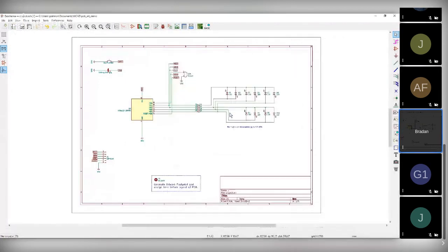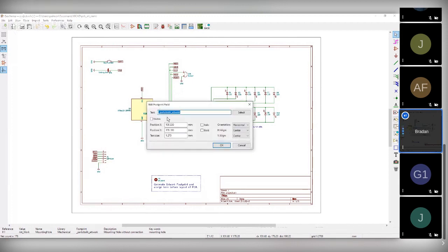How did you prevent that artwork attachment hole from being a hole? So the way that the mounting hole becomes a hole is by its footprint. And since we've now changed that footprint to be something completely different, it no longer has a hole in it. So if we went and actually looked at this, that is the footprint, as opposed to it being a 3mm mounting hole or a 2.54mm mounting hole.